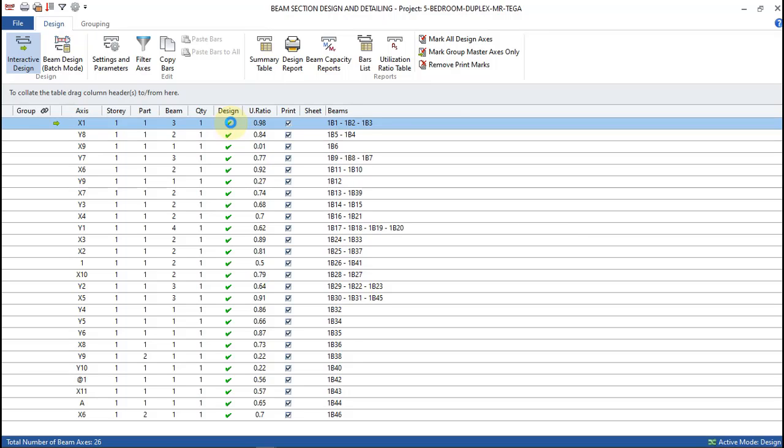Normally it's good to check one after the other, but because of this lesson, just to kill time, I'll just pick some of the critical beams like this and this one and this one and maybe one of the simply supported beams and check. But on your own, when you're doing your design, it's good to check all the beams and also check the columns too, to know the kind of reinforcement detail that the program gave to you.